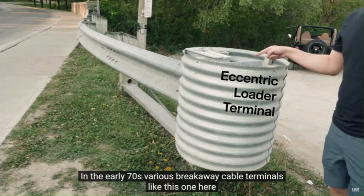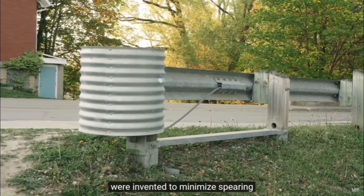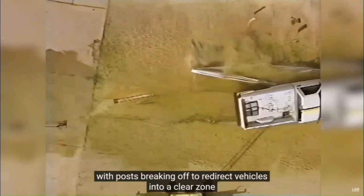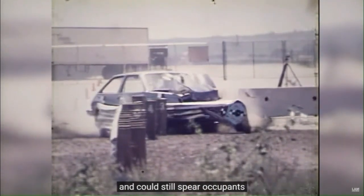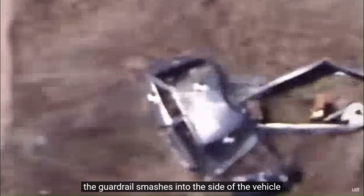In the early 70s, various breakaway cable terminals, like this one here, were invented to minimize spearing. It works by having the end roll away, with posts breaking off to redirect vehicles into a clear zone. These were used for 20 years, but phased out as they were too stiff for small vehicles and could still spear occupants. In this test footage, the guardrail smashes into the side of the vehicle and would dice up any occupants inside.